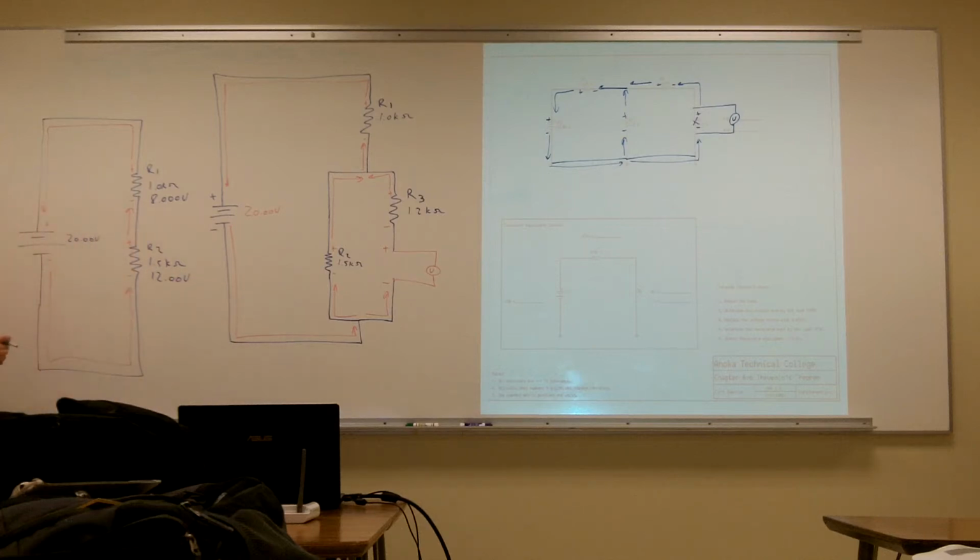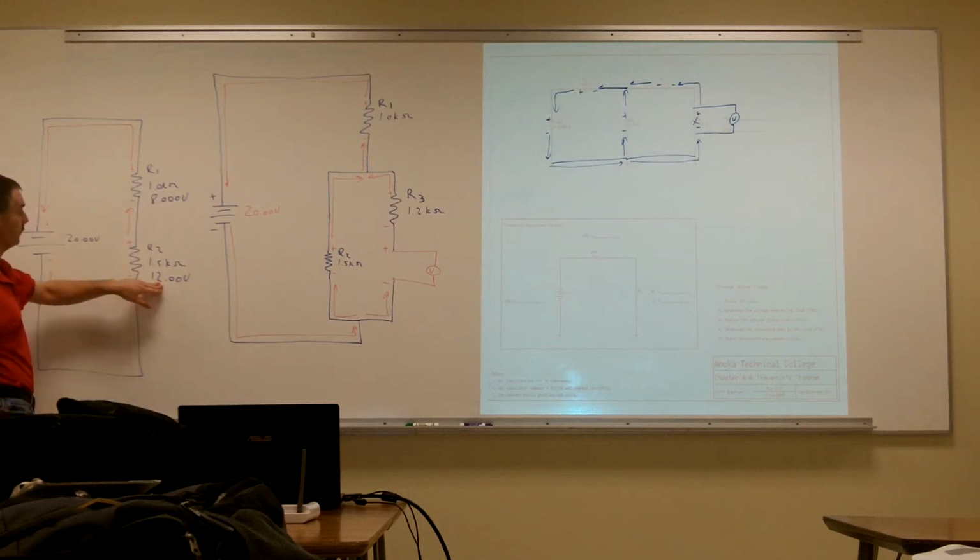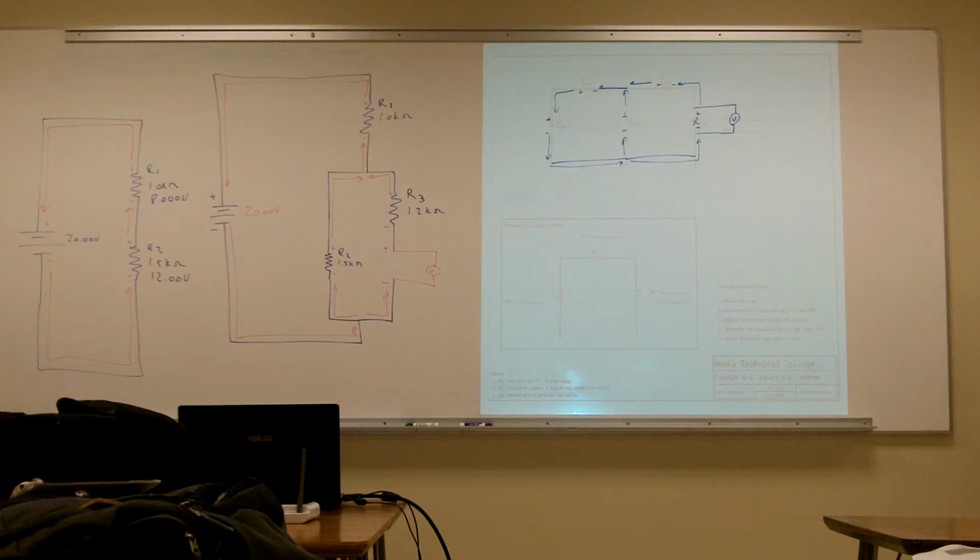And if we add up the two voltages, the sum of both of our voltage drops does equal our source voltage, so we have a pretty good indication that's correct. Also, we know that the 1.5 kilo ohm dropped more than the 1 kilo ohm, so we probably did everything okay. All right, so now we have our voltage drops.